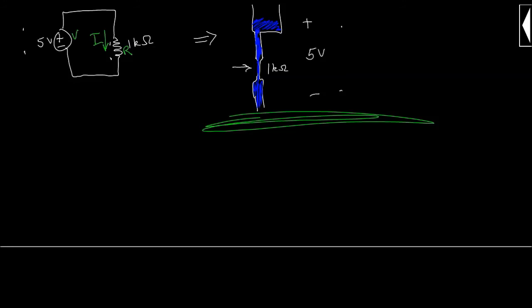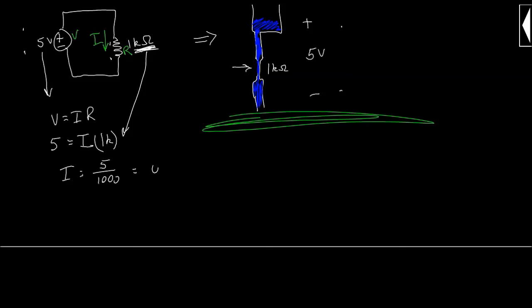across this resistor based on this voltage. So we just use our basic equation, V equals IR. We know our voltage is 5. We don't know our current, and we know our resistance is 1 kilo ohm. So I is 5 over 1,000, 0.005. So this is in amperes, and that's how you define the current as units, and that unit is in amps, which is just an A.